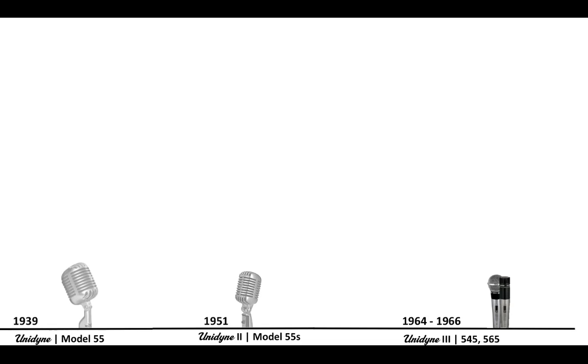But the biggest problem that dynamic microphones have is they want to capture vibration. They are designed to capture vibration, whether that's acoustic vibration or mechanical vibration. And they are perfect accelerometers to do that. And dynamic mics are normally a lot more prone to handling noise than a condenser microphone is. So you have to have a pretty elegant shock mount inside a dynamic mic.